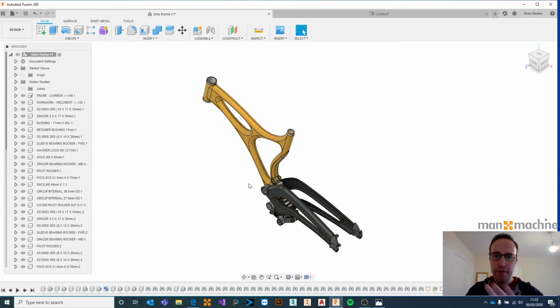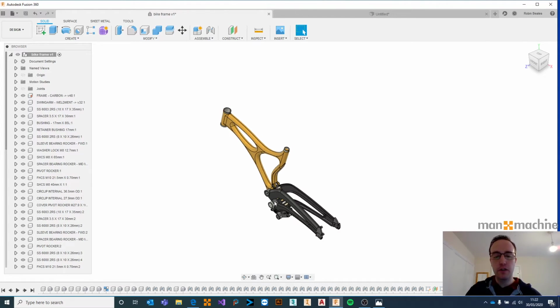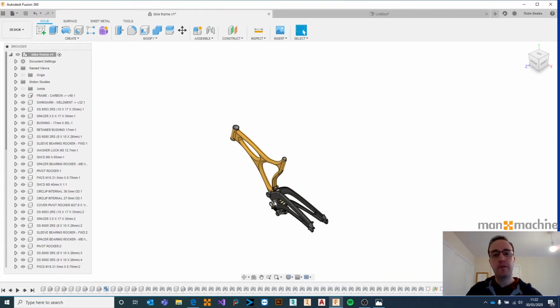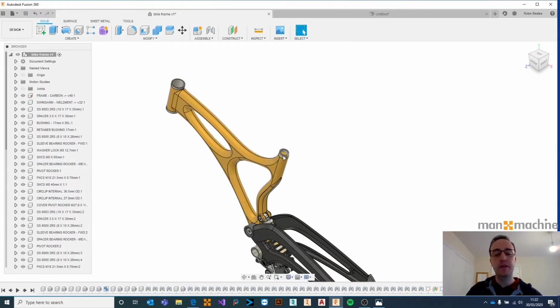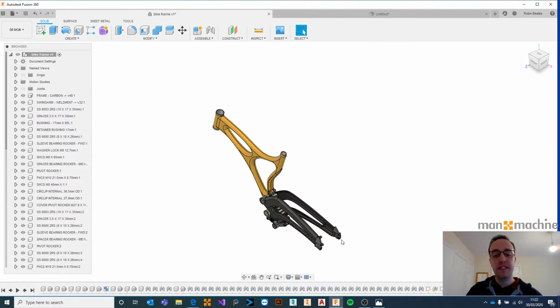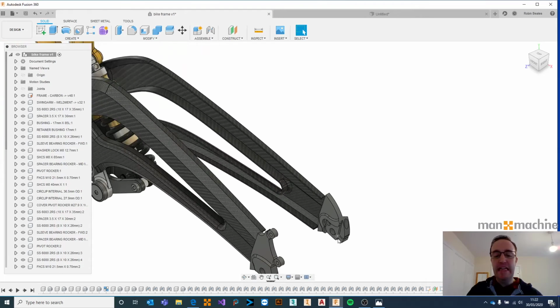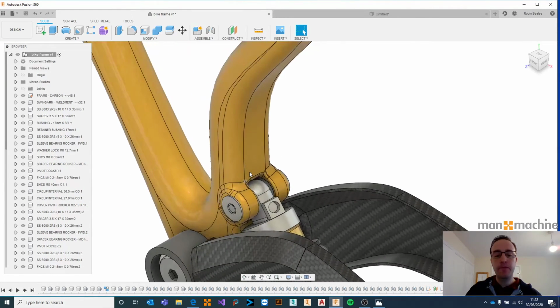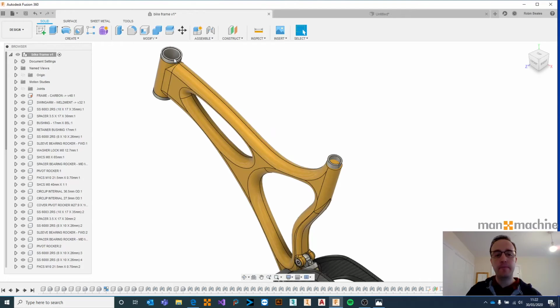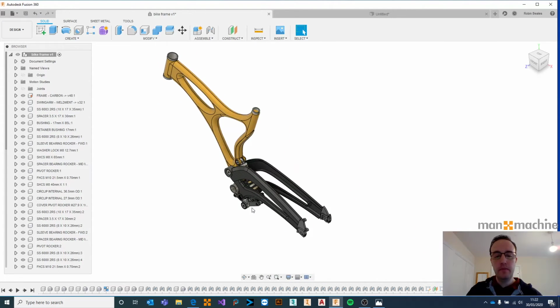So with any file that you've got open, firstly, zooming. Imagine that you're scrolling up or down your favorite web page and you want to be able to use that same functionality to zoom in and out. Well, it works just like that. So wherever you hover your mouse cursor, if you scroll your mouse wheel, it will zoom out and zoom in, okay? Wherever your mouse pointer is positioned will become your focal point or your center point for that zoom. So it's very easy to navigate around our model just by zooming in and out. Really straightforward. We hover our mouse and we zoom.